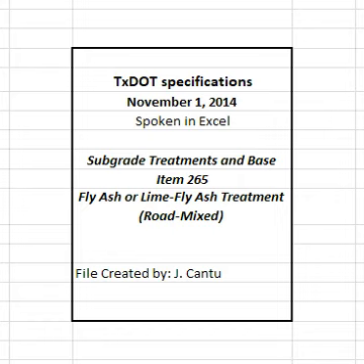2.3 Subgrade. The engineer will determine the sulfate content in accordance with TEX 145E and organic content in accordance with TEX 148E before addition of lime or fly ash. Suspend operations when material to be treated has a sulfate content greater than 7000 ppm or an organic content greater than 1% and proceed as directed.